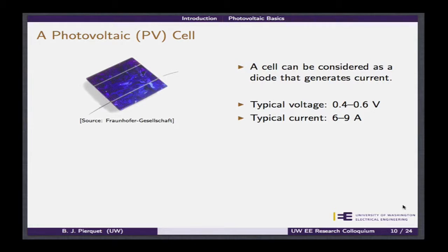But the issue being, just like a diode, it's relatively low voltage. And so one of the trade-offs is the size that you make these. You can't really increase the voltage by the cell itself. Different materials will give you different voltages. Silicon, whether it's monocrystalline, polycrystalline, even amorphous silicon, are going to have a different voltage range depending upon how they're manufactured and just process variation. But it's typically low, below a volt, or below 2 volts even for thin film.